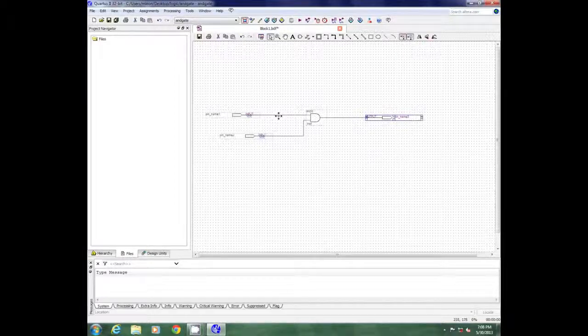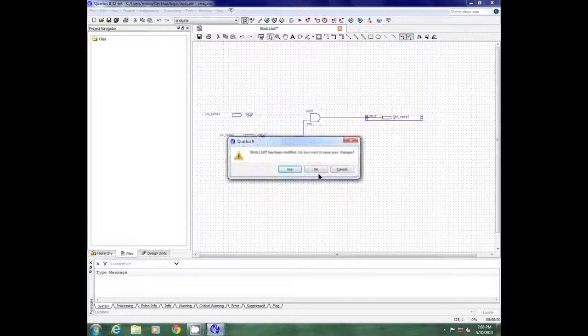So there I have my AND gate set up, and I'm going to do my first test here. I'm going to click on the icon that says Start Analysis. That's right up here. Start Analysis and Synthesis. So this is just the first step of the entire compilation sequence. This analyzes your circuit to make sure you have all the connections and the names entered correctly. It's equivalent to making sure there's no syntax error if you are doing a C program.